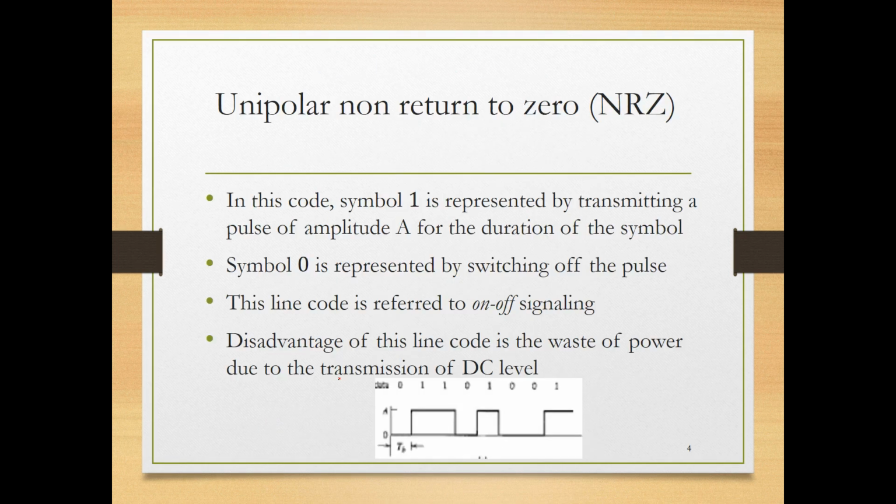So let's go to the first type, which is unipolar non-return to zero. The question can be like this: you have this binary sequence, zeros and ones, and your responsibility as an engineer is to convert this to a suitable electrical signal that can pass through your channel. Now, your system will have certain requirements. The customer you want to sell your product to will ask you, I want to make sure that there is no DC power. There shouldn't be any power spectral component at zero frequency.